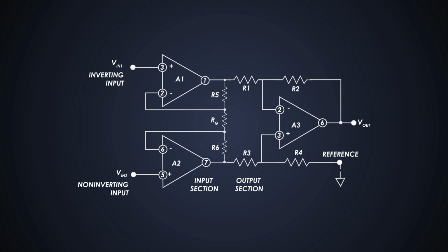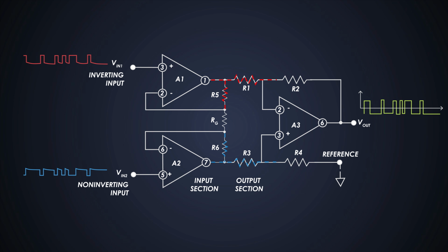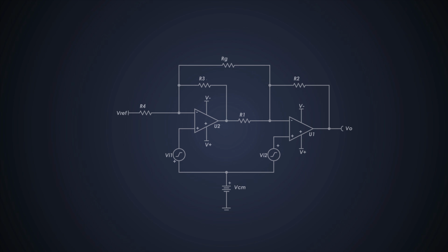Well, an instrumentation amplifier is an updated version of a difference amplifier which amplifies the difference between two signals and cancels out the common mode signal. We're using 2 amplifier circuits one after another.